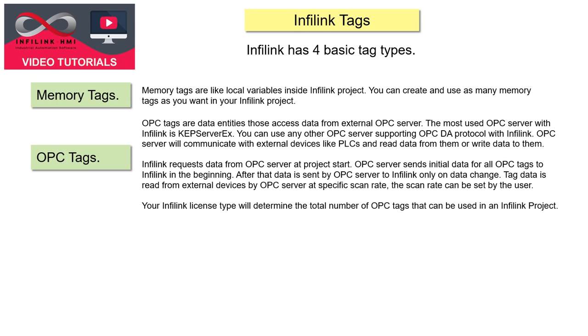OPC tags. OPC tags are data entities that access data from external OPC server. The most used OPC server with Infilink is KEP Server X. You can use any other OPC server supporting OPC DA protocol with Infilink. OPC server will communicate with external devices like PLCs and read data from them or write data to them.